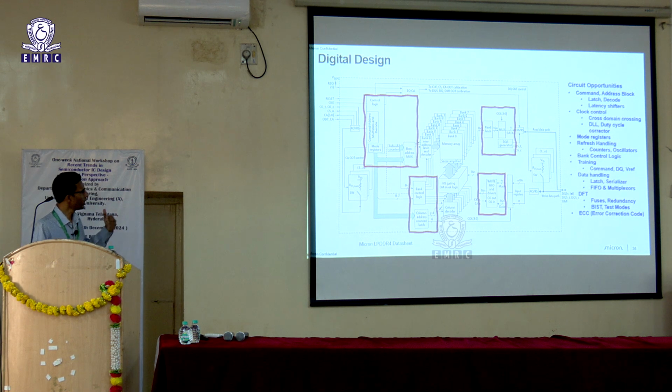And then we also have DFT incorporated, so fuses and redundancy. We are building such a large memory system, running into gigabits of memory. What if a row goes bad, or what if a column goes bad? We need to have a mechanism to repair that, and that is where redundancy comes in.